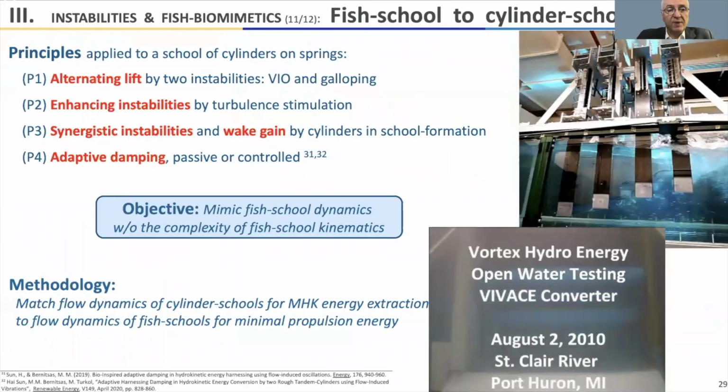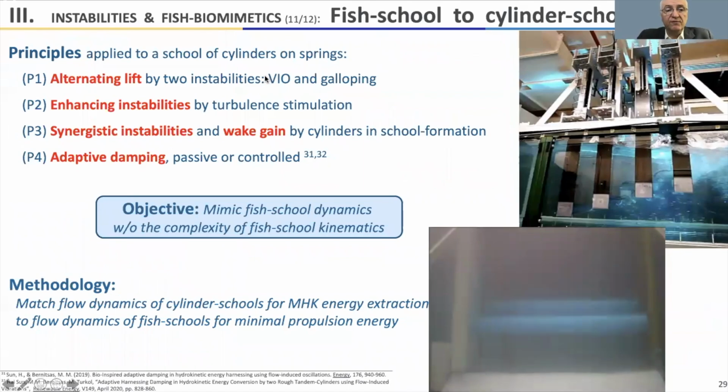The principles of biomimetics, therefore, that we are employing in the development of Vivace are alternating lift, enhancing instabilities by turbulent stimulation that we then control and harness energy, synergistic instabilities of groups of cylinders and wake gain, and adaptive damping using passive control. Again, the objective that we are achieving is to mimic the fish school dynamics without the complexity of fish school kinematics.